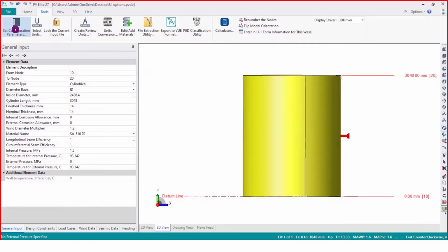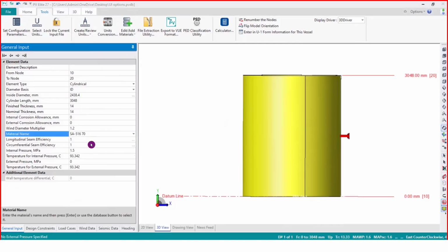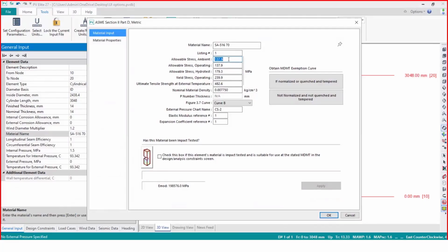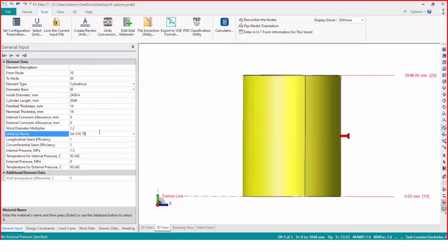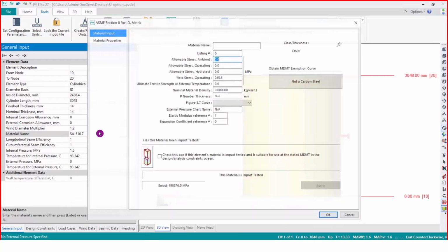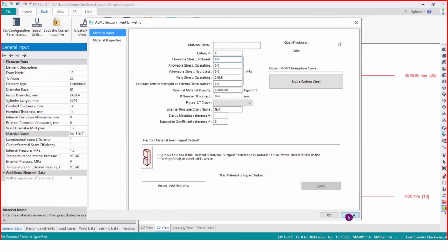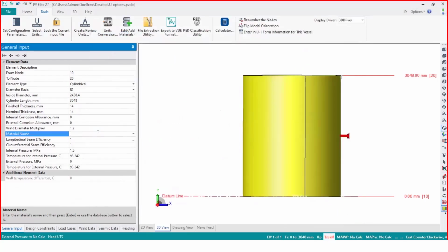So first we have to click upon this checkbox always and then we have to build the model. Otherwise it will not automatically change it. Are you getting me? Now I have to reselect the material so that the change will be applicable.